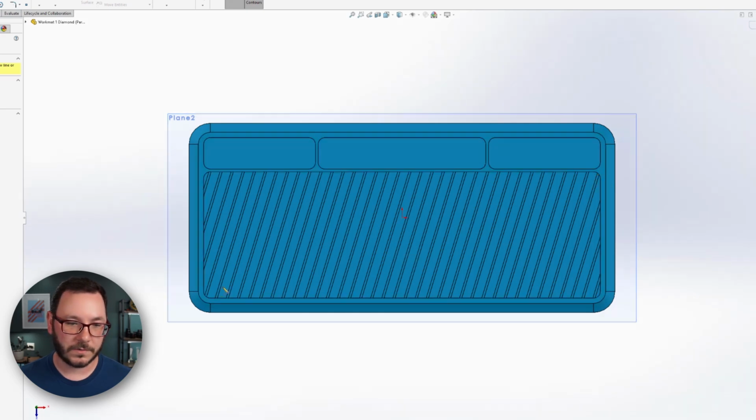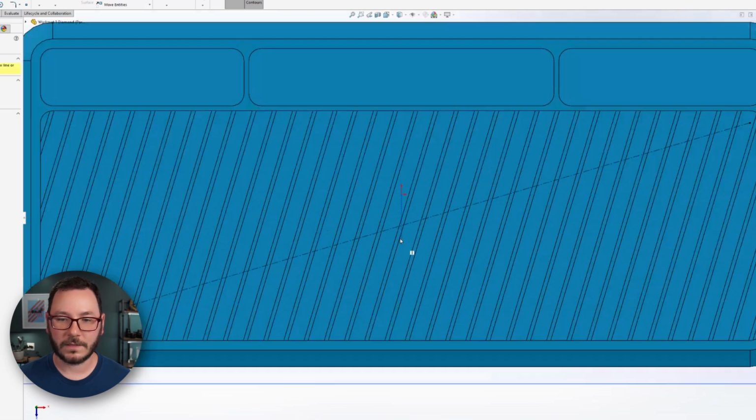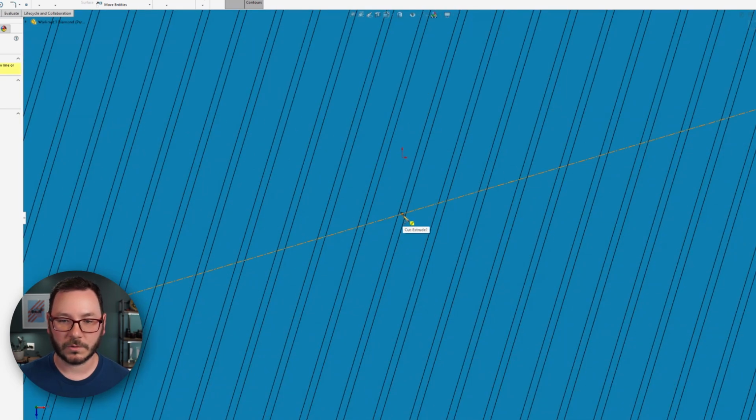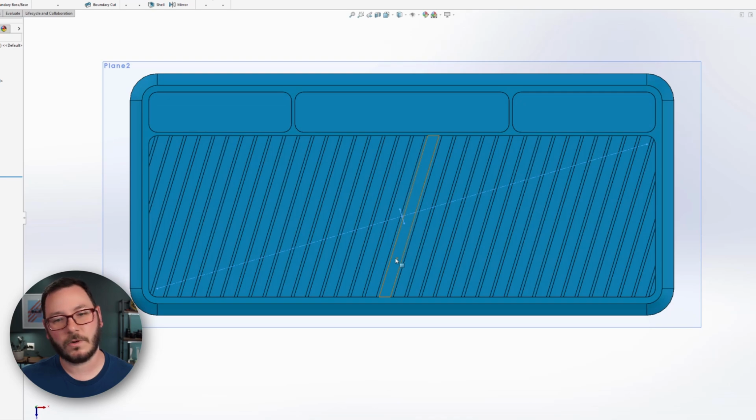And from here down to here. That guy there. Perfect. And same thing again. S key, we'll use a center point line and midpoint line, excuse me. And we'll make this a short little segment there that is, again, short enough to know what we're doing there, and we'll catch our autorelation for perpendicular. Okay, so that looks good. That should do the trick. We'll exit our sketch. Hopefully that finds its way into the corner.